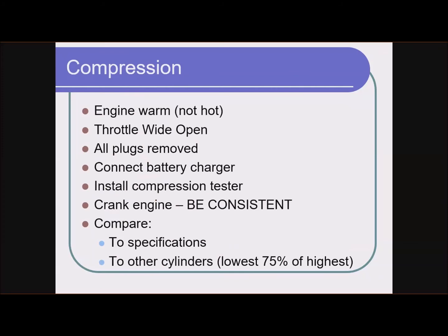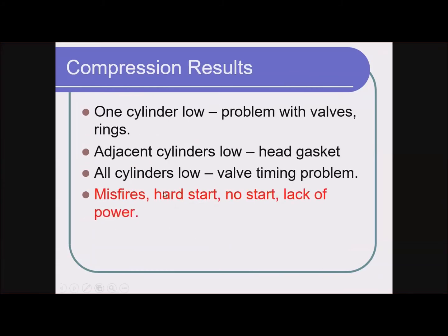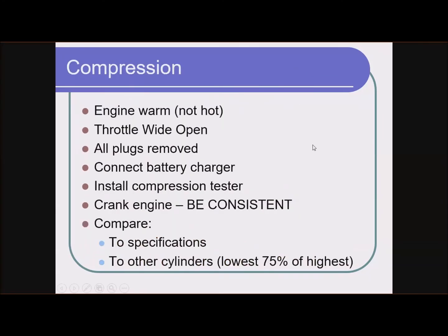Now, can you always do a compression test on a warm engine? Well, no, because if you look again at the symptoms, one of the symptoms could be no start, right? And on a no start, how do you warm up the engine? You don't, right? So you're doing it on a stone cold engine, probably 60 or 70 degrees, wherever the vehicle's been sitting.